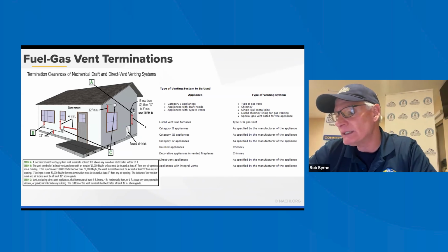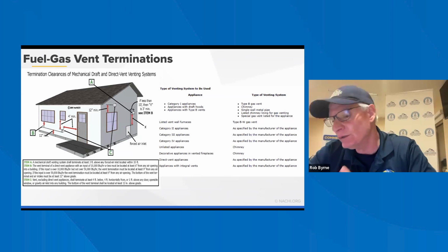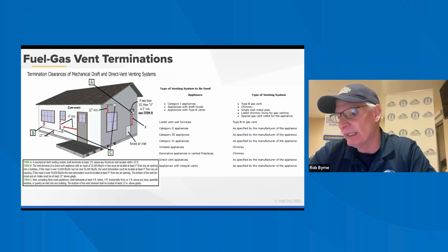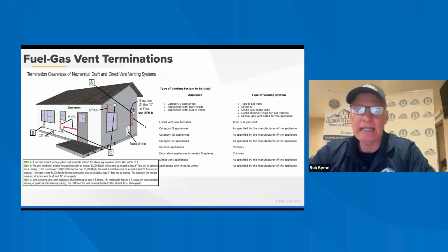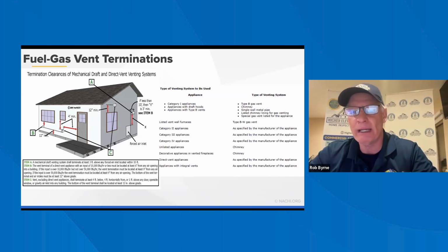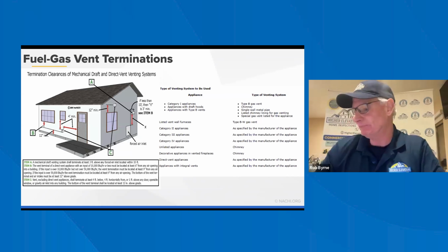Regardless, all appliances must be connected to venting systems. The venting system must never extend into or pass through any fabricated air ducts. We talked about that earlier, or furnace plenum. It must convey an adequate positive flow of flue or vent gases directly to the outdoors. That's why you never want to see that flue pipe back pitched.